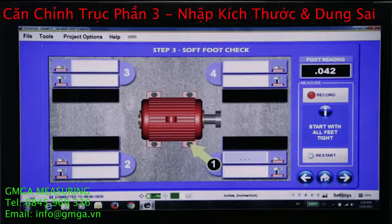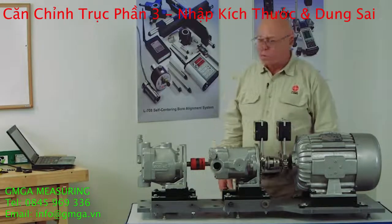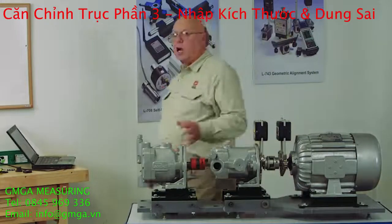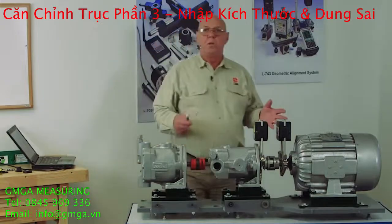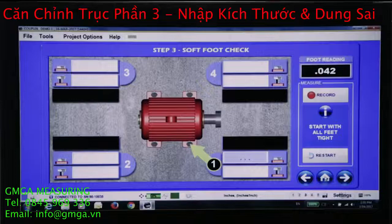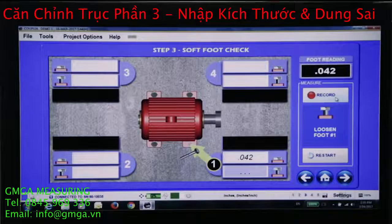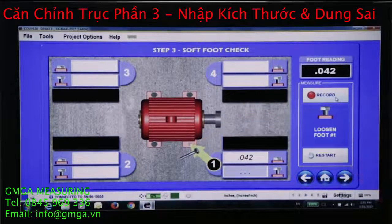Now we have what we call a soft foot routine. There's many types of different soft foot, but we can check for soft foot. The way we're going to do that is we're going to take a reading with all the bolts tight, and then we'll loosen the bolt, and it'll tell us how much change we have. So I got all the bolts tight. I'm going to record that. Now you see it's telling me it wants me to loosen this bolt.